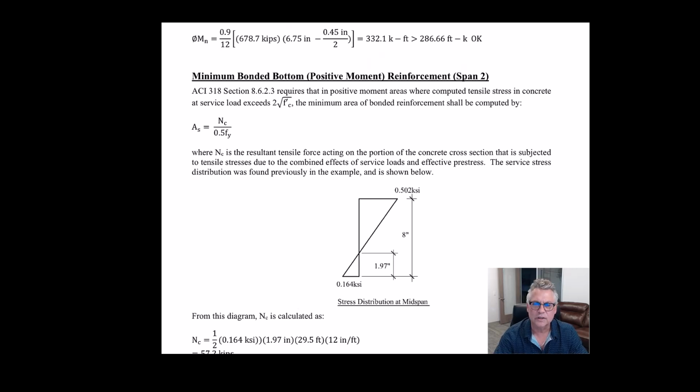And because we're using an average stress, knowing that we have higher localized stresses near the column, we limit our two-way slabs to 6 square root f'c. What are we doing adding rebar at 2 square root f'c?